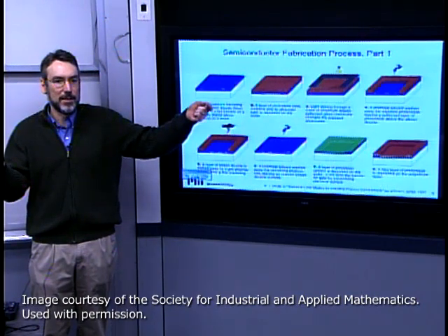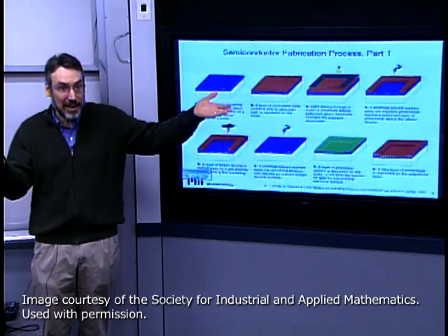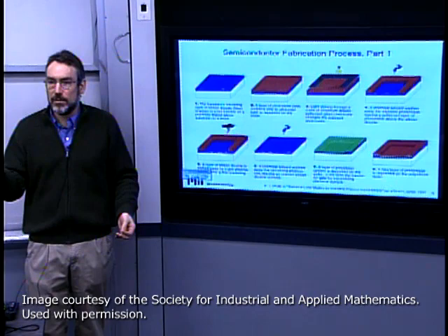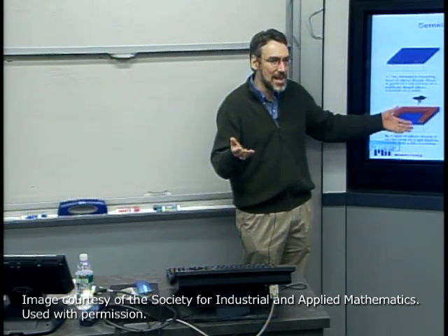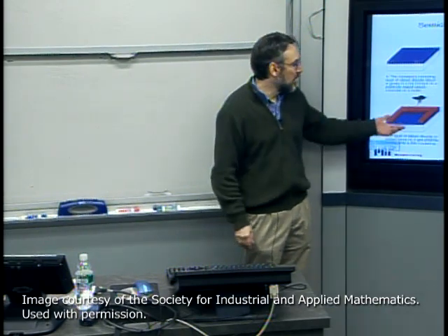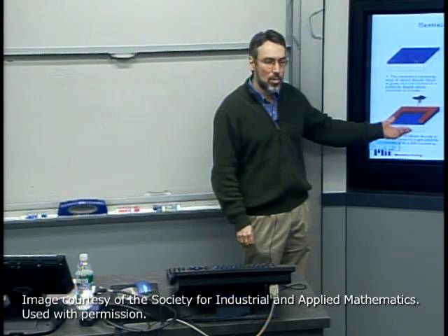or variability, which is not bad. That'd be great if I got whatever that percentage is, 0.05% or 0.02% or whatever. I mean, that's amazing, but it would magnify by the time I etch down, even if I could etch uniformly. There's just no way, most importantly, to be able to know when you're within 100 angstroms and be able to stop controllably at that level.